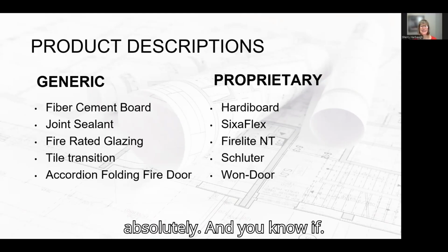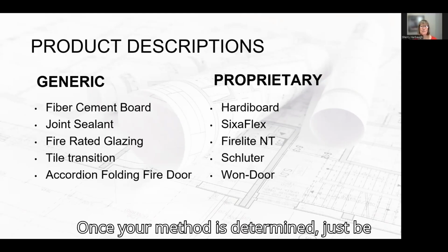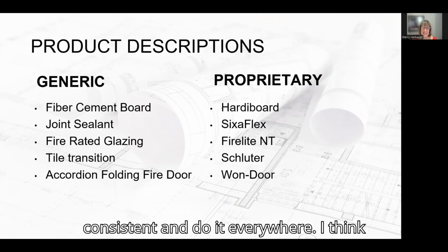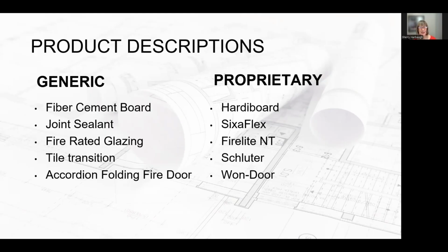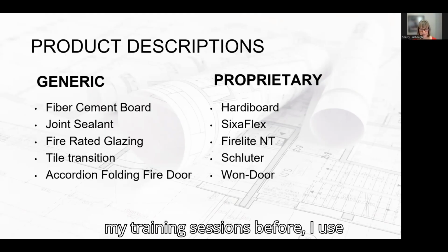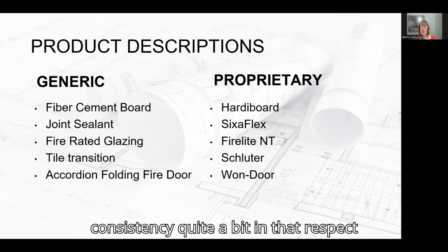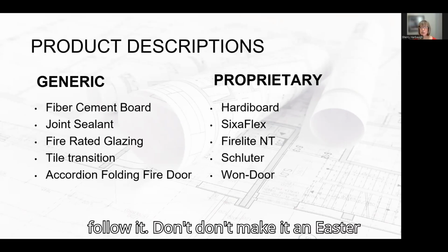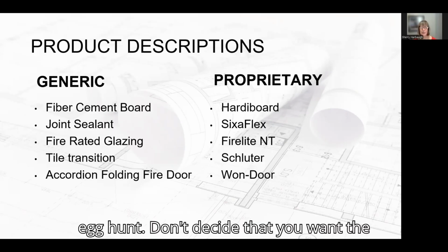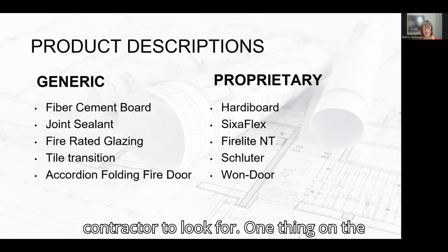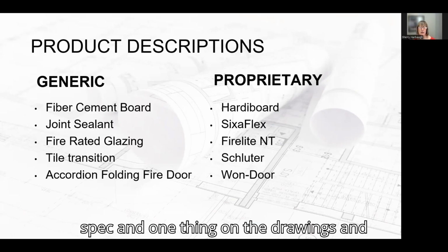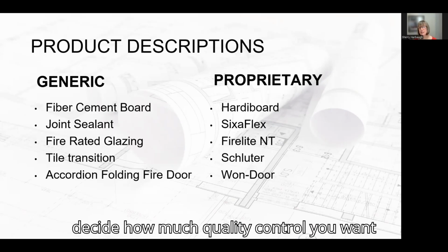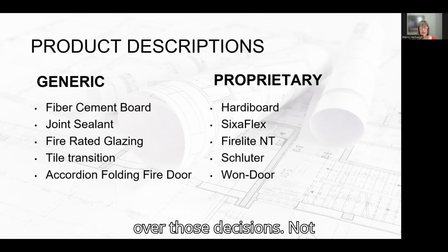Yeah, absolutely. Once your method is determined, just be consistent and do it everywhere. If you've listened to my training sessions before, I use consistency quite a bit in that respect. Just choose a line and follow it. Don't make it an Easter egg hunt. Don't decide that you want the contractor to look for one thing in the spec and one thing on the drawings. And decide how much quality control you want over those decisions.